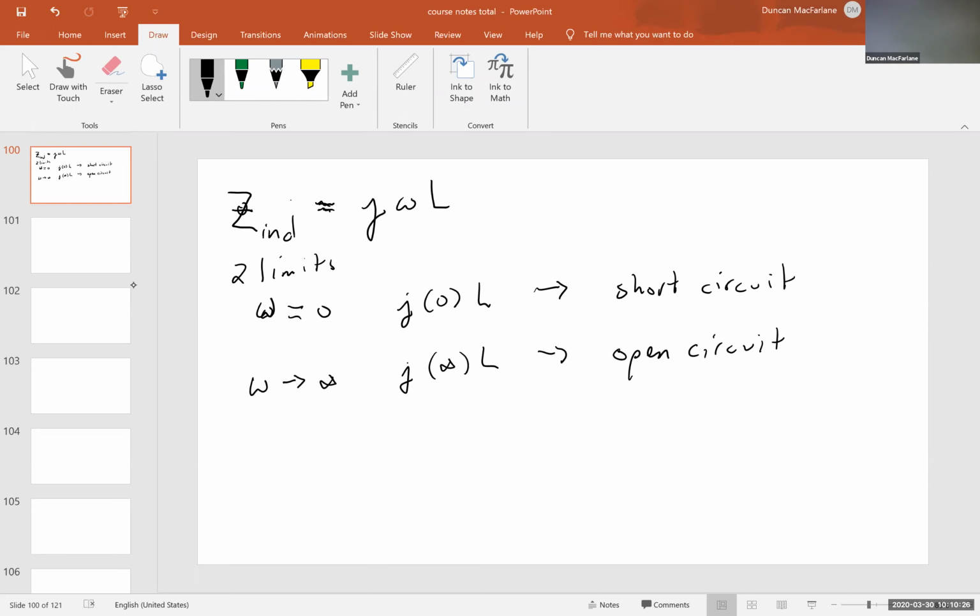So the idea is you connect your inductances and your capacitances in such a way that you route your signals on the basis of their frequency. And the basis of their frequency is filtering. You can use these frequency dependent impedances to sort one frequency from another frequency.